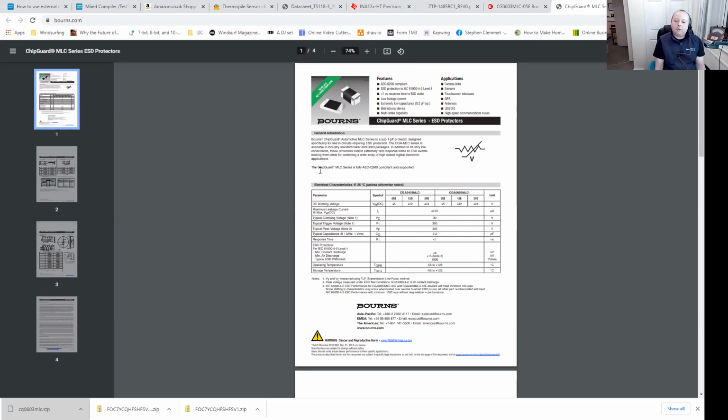Oh yeah, you can get some super fast devices for sure, but don't forget, if they're going super fast, you're going to have ringing, and EMF problems, EMI, yeah, absolutely. And also things like skew effects, and if you have tracks even moderately long, you're going to be in a world of fun. If you look at DRAM, if you're doing fast memory DRAM designs, the track length becomes quite critical.